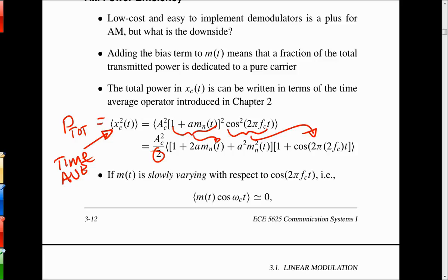So the idea is to back up and say, can we dispense with 3 terms? From the time average operator notation, in the modulation theorem, what does this double frequency carrier do when it operates on all 3 of these guys here? For the modulation theorem times a baseband signal, which is what the message is, or the message squared, it'll shift them.